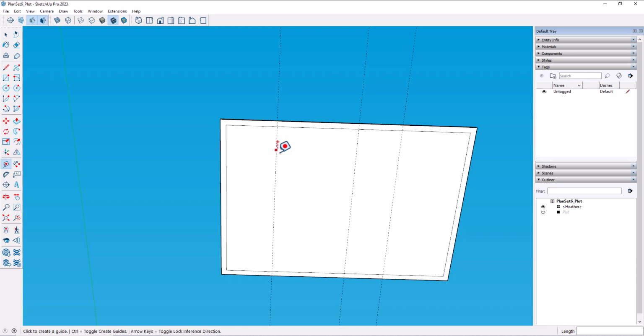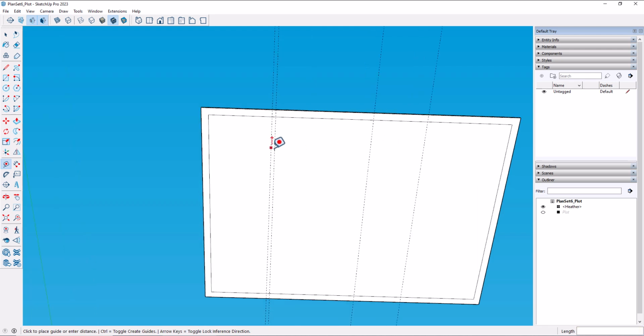Now these are the center of our footings. We're going to go to each side 6 inches, just on all 3 of these. And then to create the bottom row, we're going to go from the top here, going to go down. Make sure that your line is green. That means it's going to be parallel to that green axis. And this is going to be 11'3".